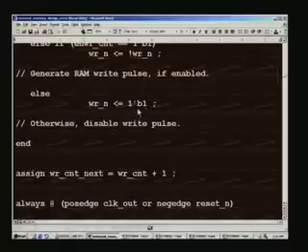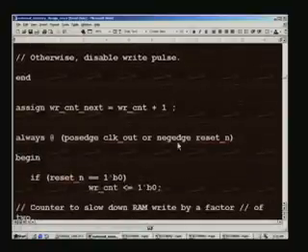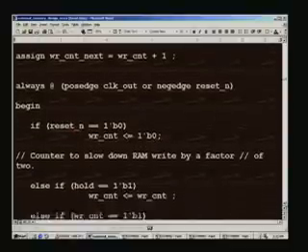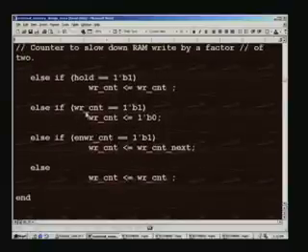Otherwise you just take it to the safe state of 1, being active low here, and then what we need to do is increment the counter, and this is the advanced increment, in this always block at the positive edge again. So, what we do is we reset the counter to start with, and when write count is 1, that is the counter is running between 0 and 1, whenever it is 1, that is the identification of the second clock, only then will write count be forced to 0.